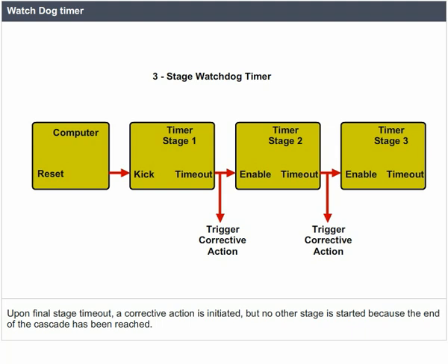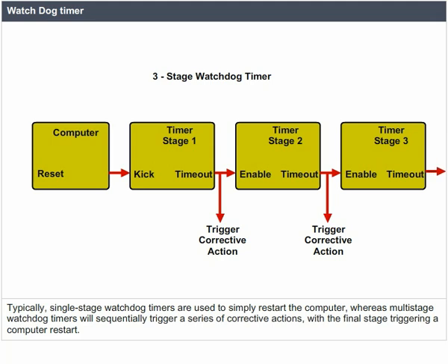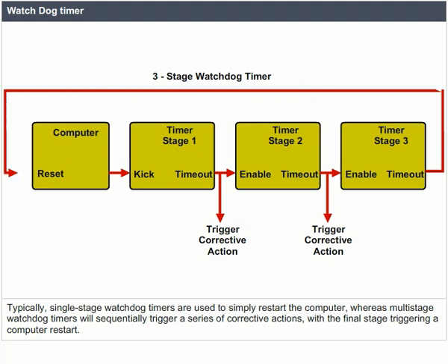Typically, single-stage watchdog timers are used to simply restart the computer, whereas multi-stage watchdog timers will sequentially trigger a series of corrective actions with the final stage triggering a computer restart.